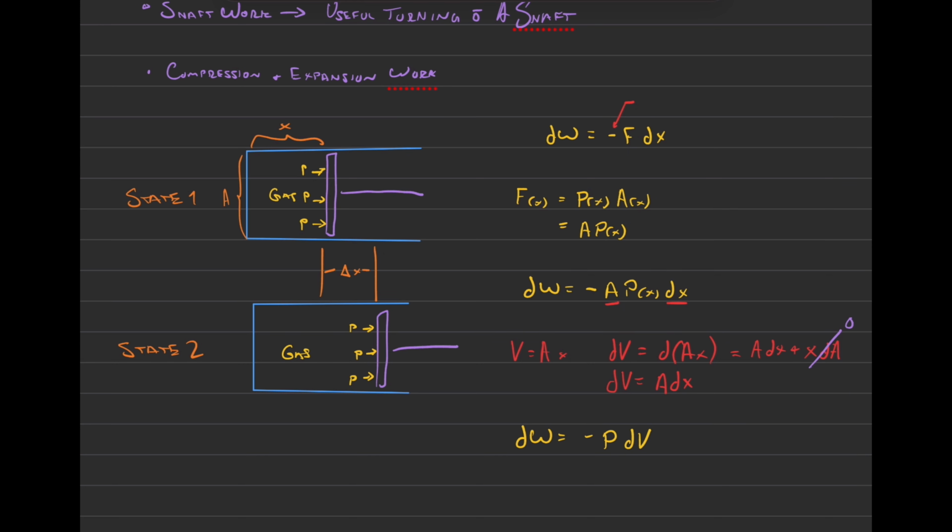Now, that's called compression and expansion work. Why? Because the work is done on the control volume as the gas, as a piston, or you could think of it as any flexible control volume, in the sense where the total volume is not held constant. As that volume expands against, and pushes against its environment, that push does work against the environment. And when the environment collapses against the control volume, that environment does work against the control volume.